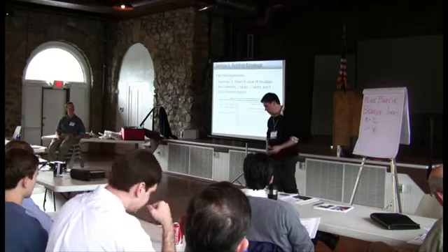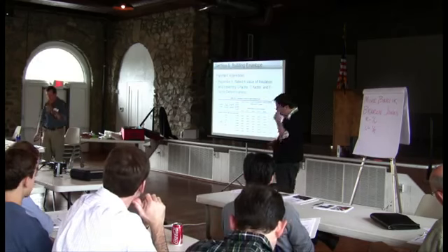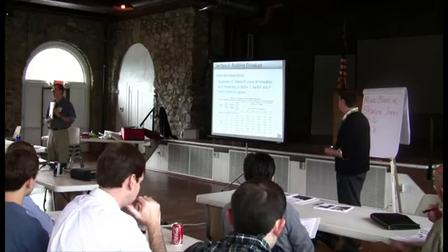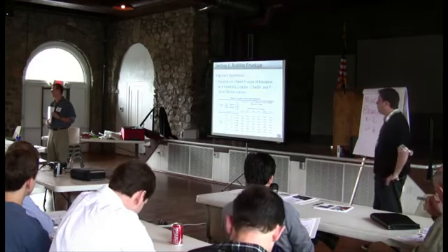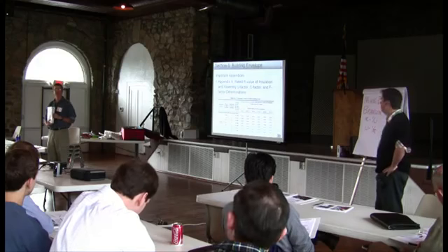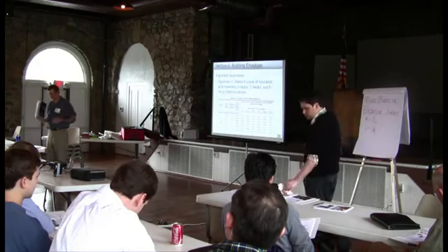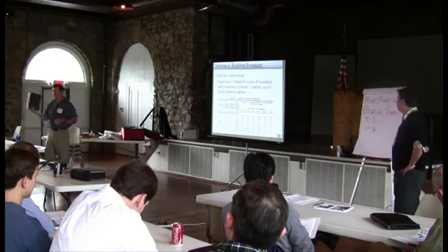So the other thing that's really helpful for designers is that ASHRAE has some very good appendices. Appendix A in this has basically got tables and tables of just about any assembly that you can imagine, where someone has already calculated the U factor and performance of it and R value. So you don't have to start from scratch on many, many things.